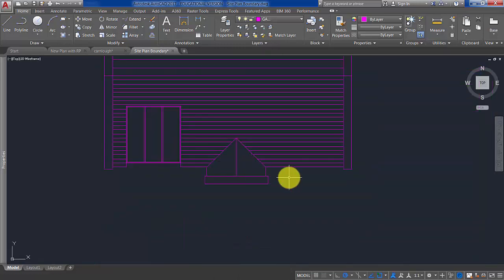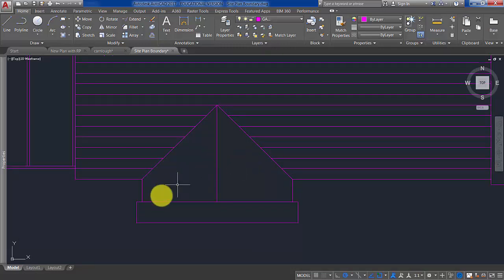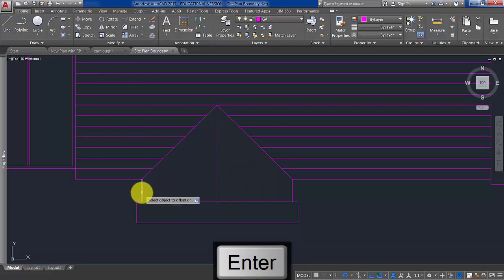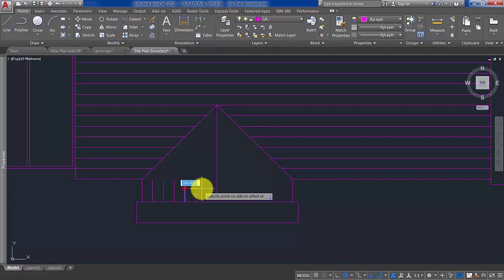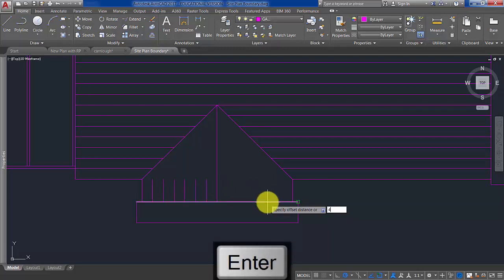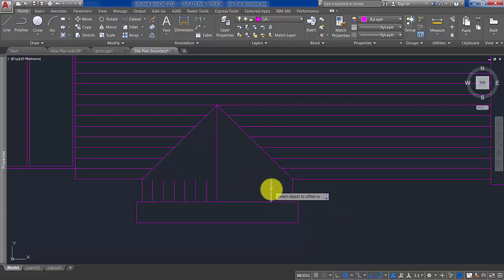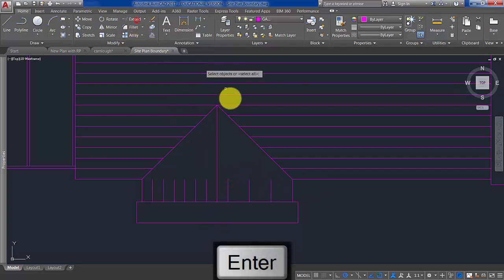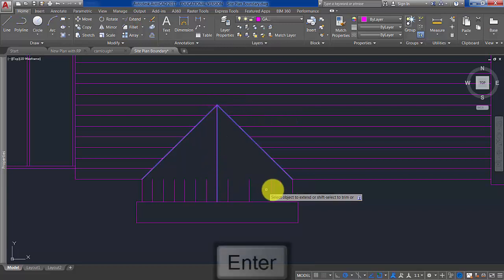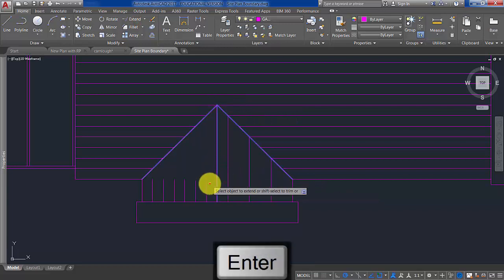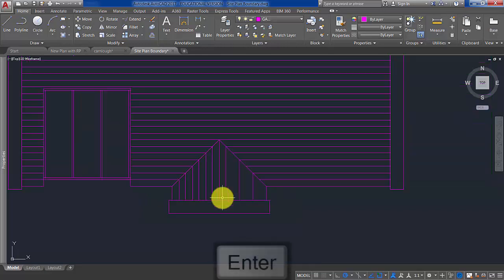And then the one element that needs to be finished still is the part down here, so that's offset by 200 on this side, because there's a small distance there. That shouldn't be too hard to do. And let's do 400 on the other, and that will be every other row it meets up with. And let's use the extend tool and just pick up those lines like that.